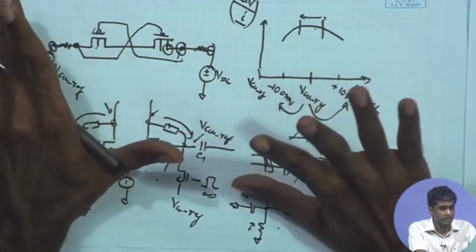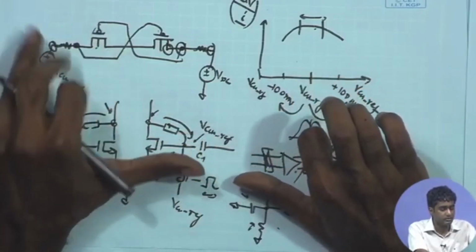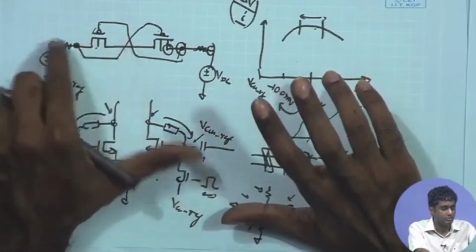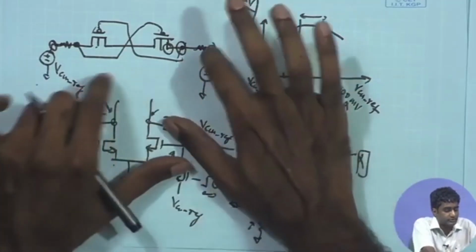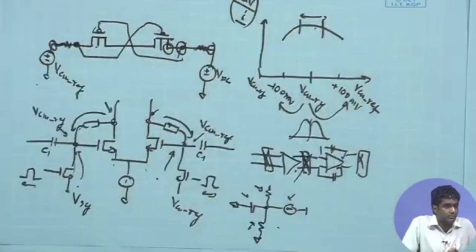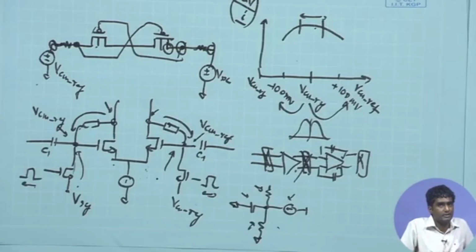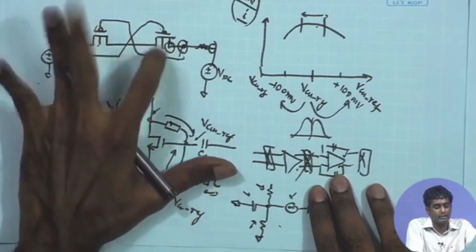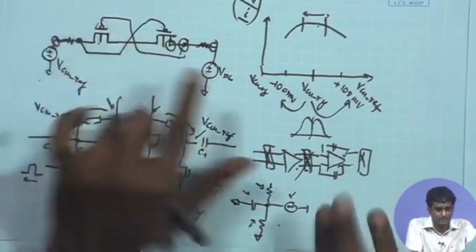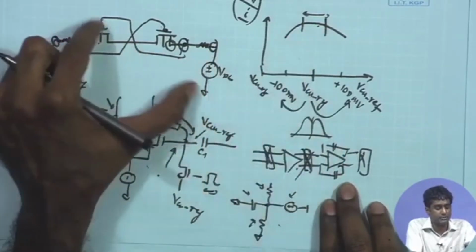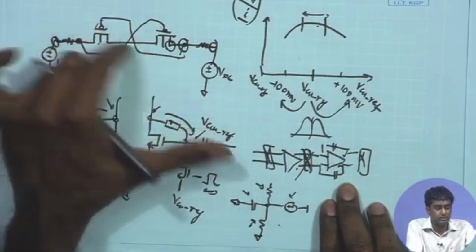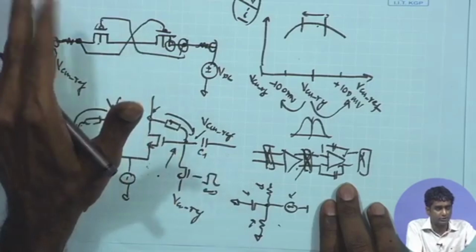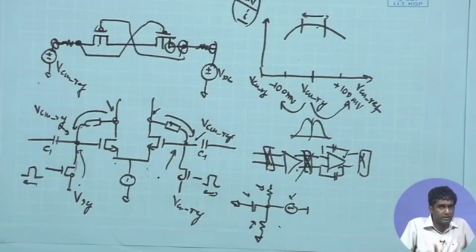leakage components are not very significant, especially the gate to bulk leakage, and likewise the bulk to junction leakage. They are not very significant. As the potential difference starts increasing, both of them will have more leakage components coming into the picture. Here we are interested in the source to drain current; other leakage components like junction to bulk leakage or gate to bulk leakage will destroy the characteristic that we are looking for. As the potential difference across the gate and the source, or gate and the bulk, increases, all those leakage components increase exponentially, because that is mainly based on tunneling effects.